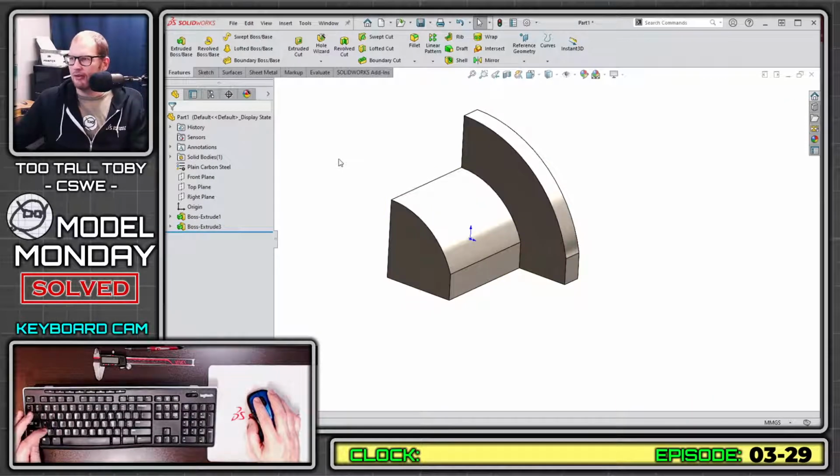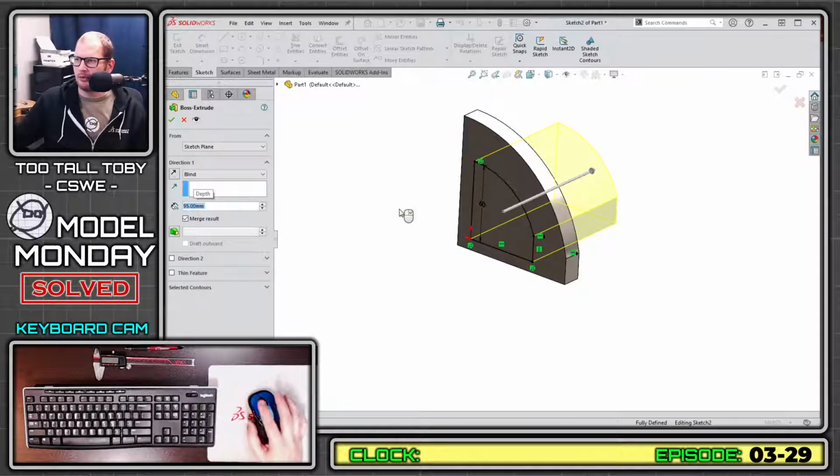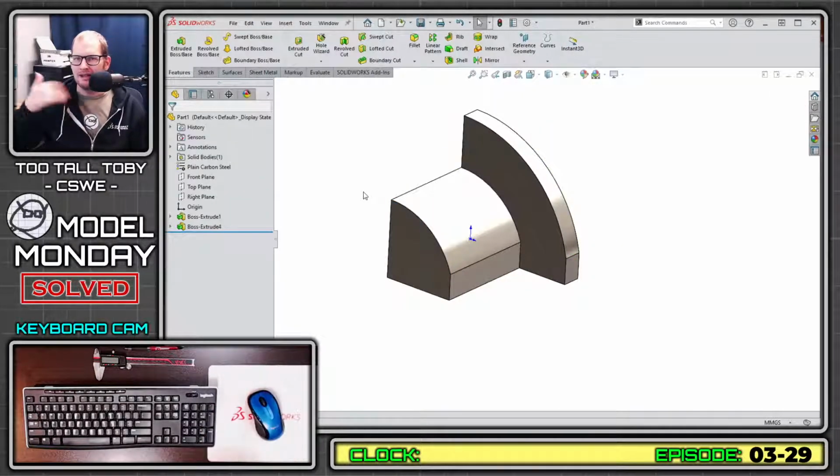And so in real time, it looks like this. S key, extrude, 95, enter once, move the mouse a little bit, right mouse button, reverse direction, right mouse button again. These are very fluid movements, but it's really a combination of several little steps that I've learned through practice, anticipating what's going to happen next. I know from experience that if I right mouse button right away, it's going to finish the command. That's not what I want.